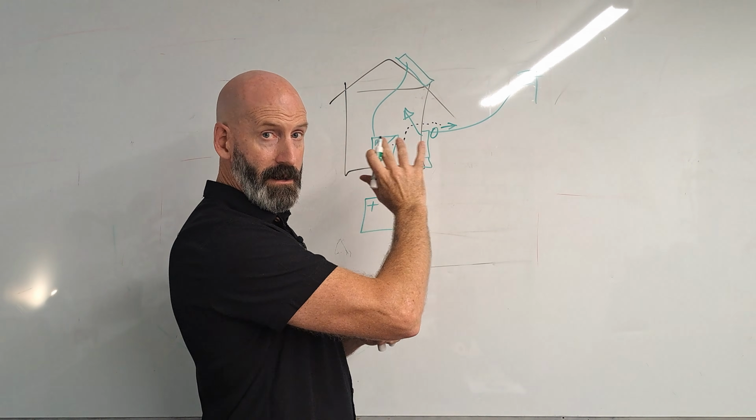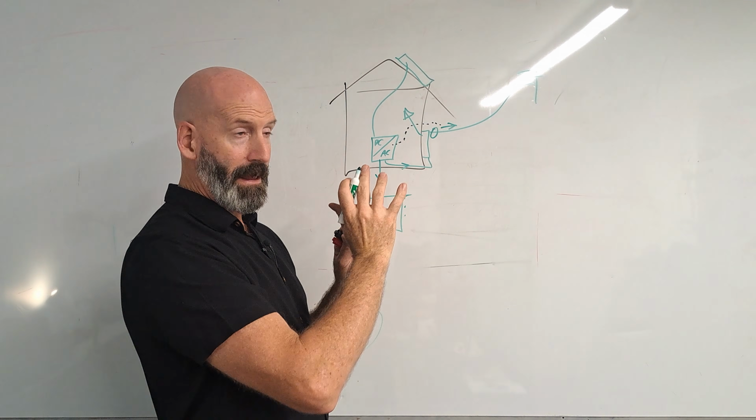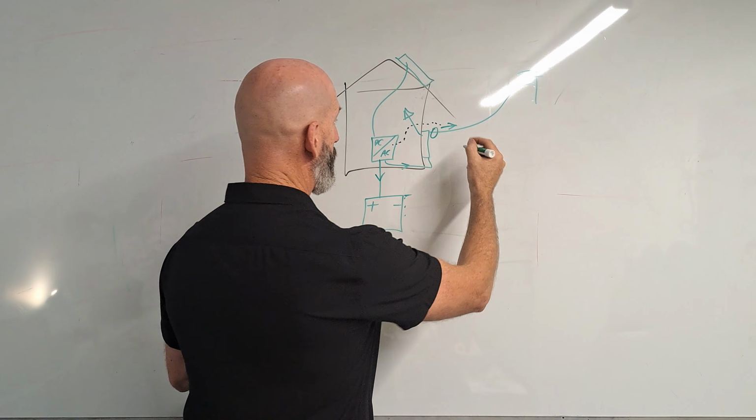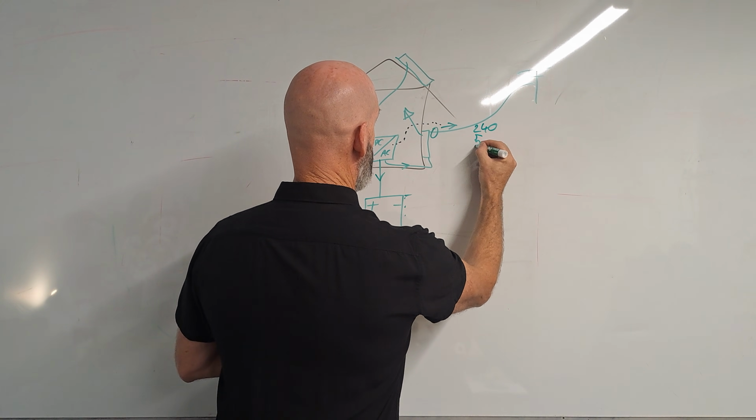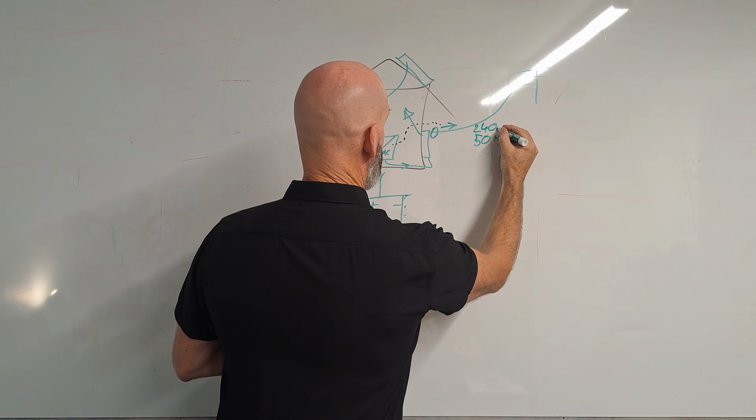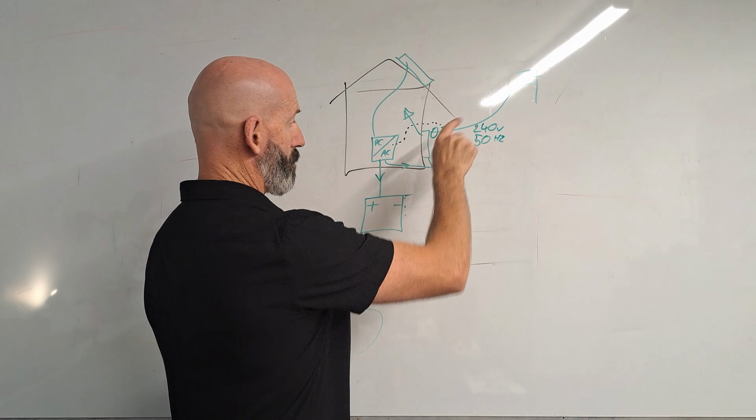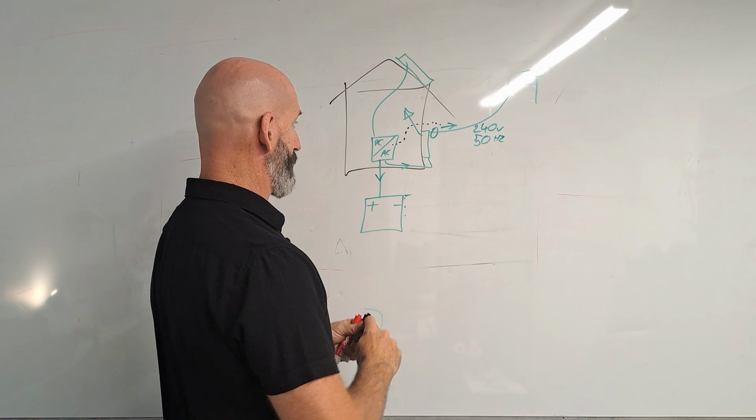So they're not designed to run long-term disconnected from the grid on a hybrid inverter. They're not built for it. So that's one thing. It needs its 240 volt, 50 hertz regulation basically managed by the grid.